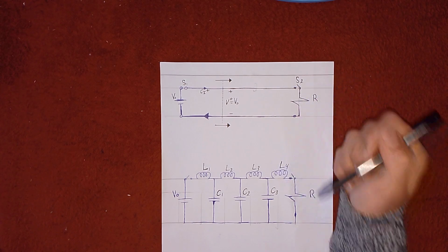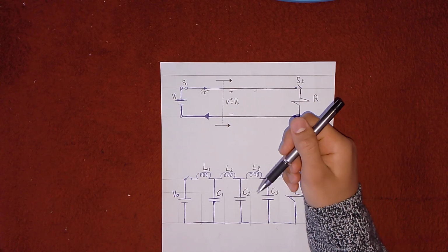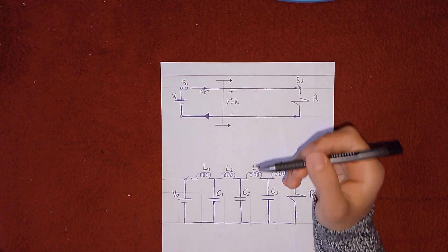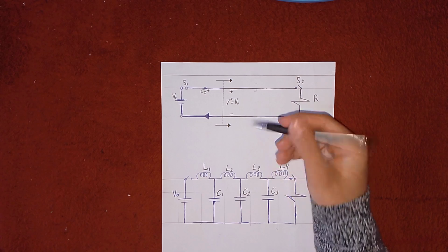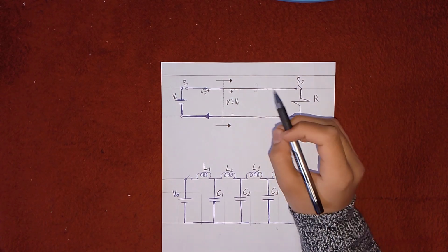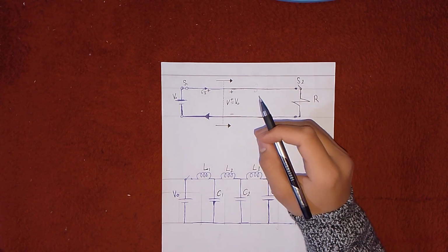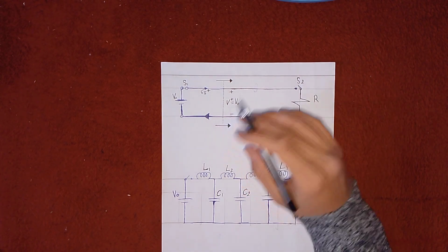Both current and voltage are discontinuous across the wavefront. This means that at the exact boundary of this traveling wavefront, where the wave is just arriving at a certain point along the transmission line, the voltage and the current suddenly jump from 0 to a certain value.